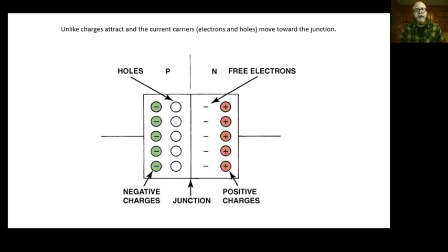And if your meter has a diode check function, that's really all that's happening. It's just trying a little bit harder to pass current through whatever circuit, whatever component you're holding your test leads to. So when we put our meter onto that diode check function, it ramps the voltage up to 6 or 7/10 of a volt, 0.6 or 0.7, which is substantially more than 0.3. We've doubled our voltage. So that is enough to actually bias a regular diode. An LED, it's not enough to bias it, but it's enough to allow our meter to give us some information, which I will show you in a moment.